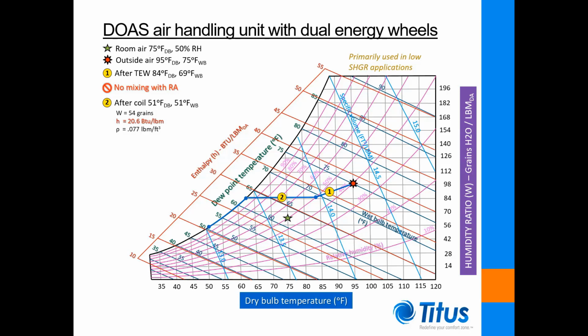Conditioned air leaving the cooling and dehumidifying coil enters the desiccant wheel. Moisture from the conditioned airstream is transferred to the return air. In turn, heat transfer from the return air raises the dry bulb temperature of the conditioned air with little change in the total enthalpy of either airstream.